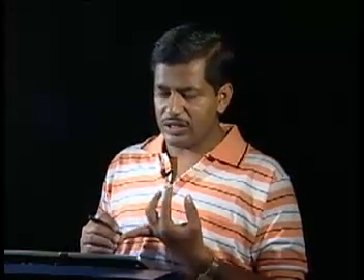Okay. So with this, let us now close our exercise that we did with respect to a very simple finite element formulation using hat functions, and we saw how we construct the element calculations, how we apply the rules of assembly to form the global stiffness matrix and the global load vectors, how we apply first the Neumann boundary conditions, then the Dirichlet boundary conditions, whether we have to check for consistency or not, that has to be problem dependent, and we further extended the problem to include various types of boundary conditions, and also finally the case where there is a distributed spring attached to the member.